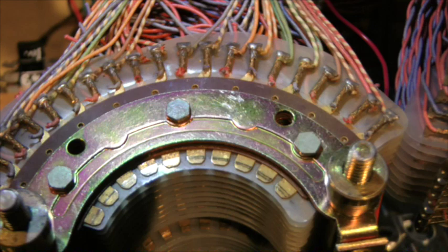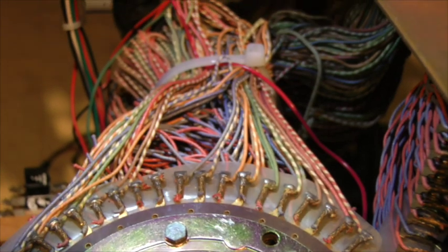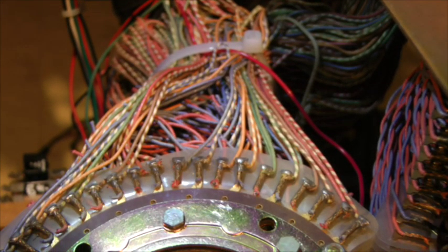Each bank assembly has 600 of these little metallic contacts called terminals, which are electrically isolated from each other. At the rear of the bank assembly, these 600 contacts are connected to 600 wires, which are cabled over to 200 line circuits. It follows that each line circuit requires a 3-wire connection to the bank assembly. These are the tip and ring transmission path wires and the sleeve control wire.